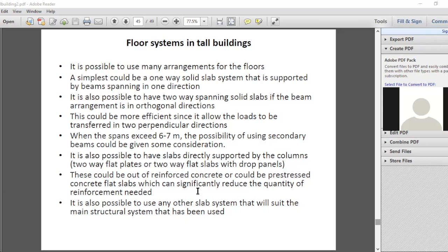structurally as a composite material with the decking sheets. So for any span, you need to have a reasonable depth. So you'll find that the decking sheet is profiled in such a way that you will get some kind of ribs. And I can again show you the shape. So basically, you will have a system where you have the steel beam, and there will